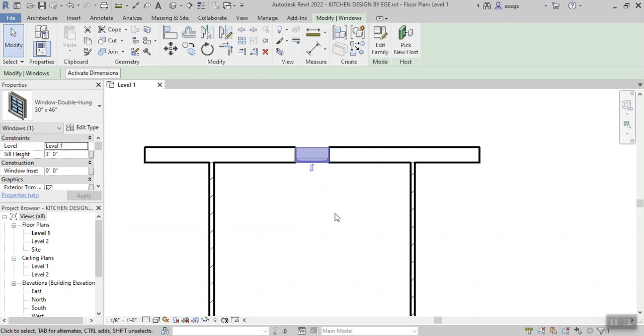That indicates outside of the window. Wherever the double arrow is, if it's below the exterior wall, that means the window is located wrong. The double arrow should be above the wall, because the double arrow indicates the exterior side of the window. So move your cursor on it and click on it. Now it is correct. Now we have a window sash inside, and the window is located outside. That's perfect. Again, save your work.